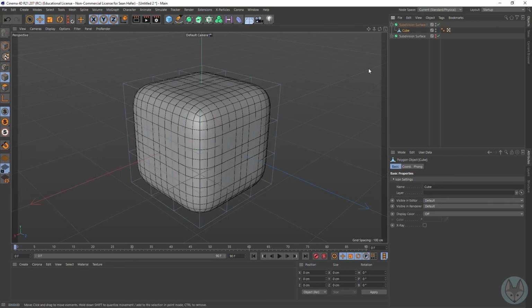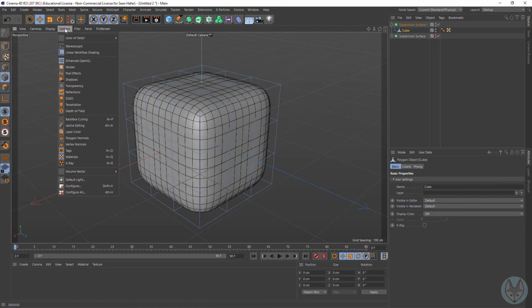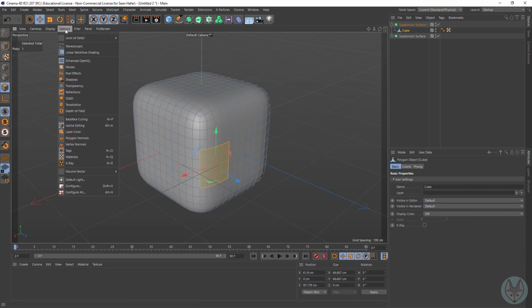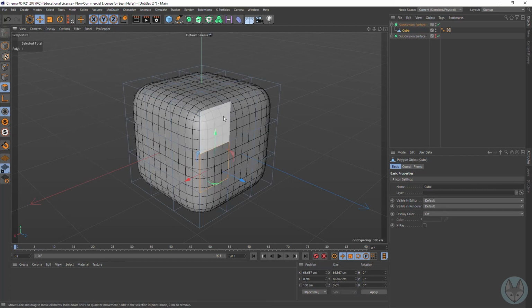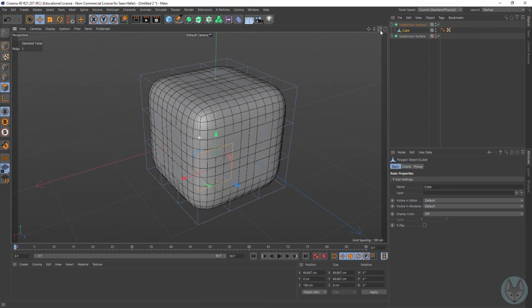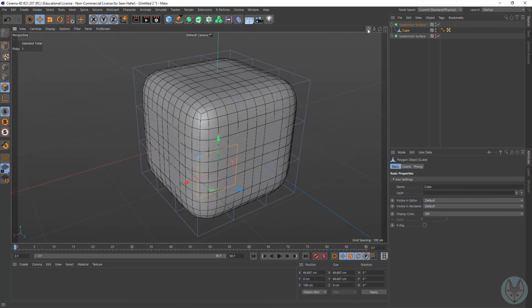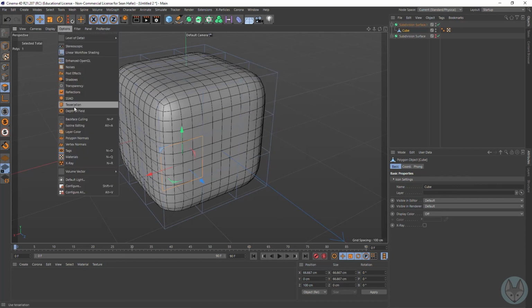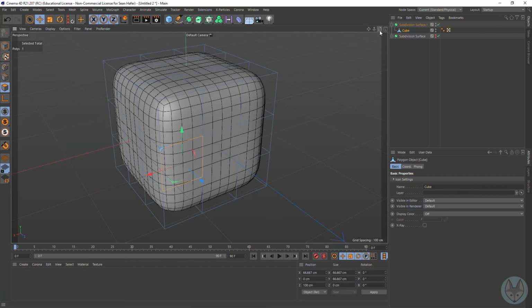Now this is also where your options here of the isoline editing are, if you want to grab and see your polygons sort of curved on the object, you can use that isoline editing. I like to see my actual mesh of my polygon object, so I turn that off. So that's what I'll be doing here, is using that tool that way. You can choose how to use it how you want, but if you get confused by what I'm selecting, that's why I just have that isoline editing turned off on mine.